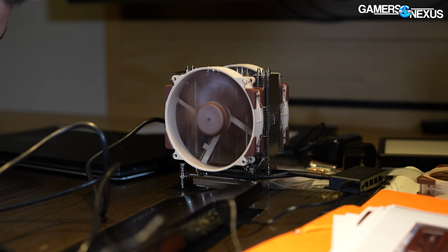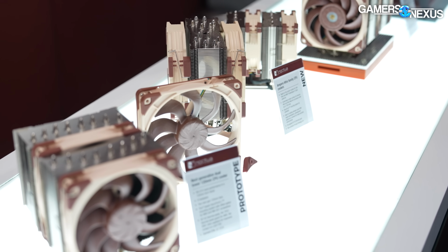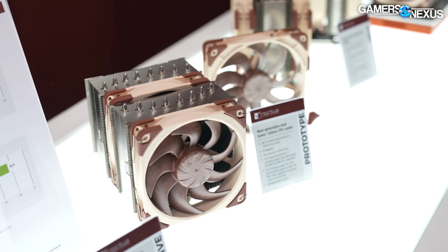This is extremely important, especially from a noise normalization perspective, because your fan may sound great in free flow, but if it has a problem dealing with those turbulences and back pressure, it may sound really bad on a heatsink. And that's where the real fine-tuning begins, that you make sure that that fan and heatsink really match nicely from both performance and acoustic perspective.